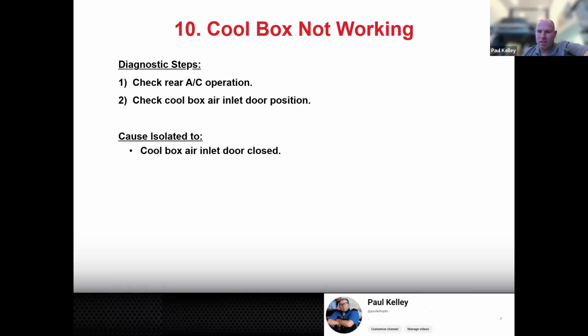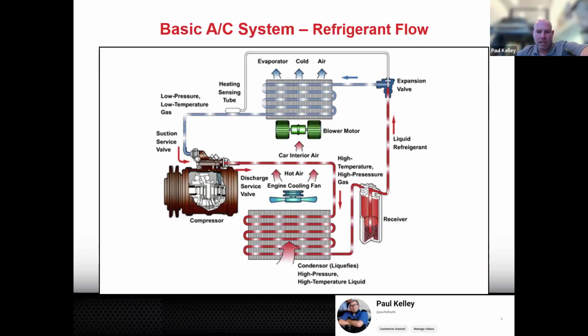All right. Now, if you think you're ready, I just want to make sure that I give you a little prep time, and then I'm going to tell you exactly how you're going to do the stage 2 of diagnosis. So let's run through this one final time. The compressor, remember the compressor sucks in the refrigerant from the low side. It should be a vapor when it pulls it in. It's going to make it into a high pressure, high temperature vapor when it leaves. It's going to go to the condenser, where it's going to condense into liquid. It's going to liquefy it. The condenser fan is going to pull that heat out of there.